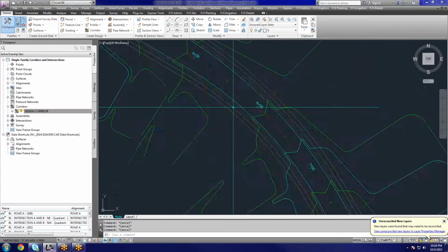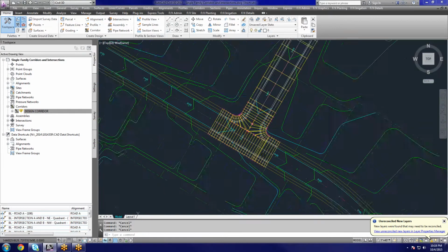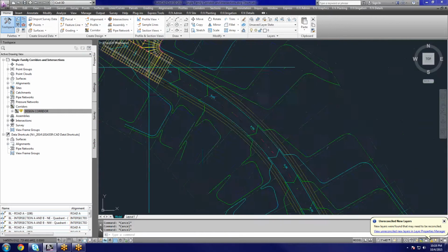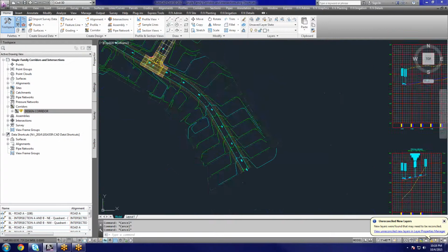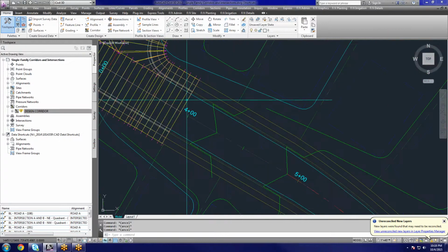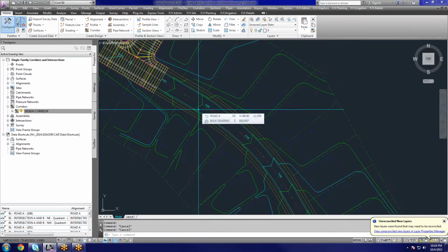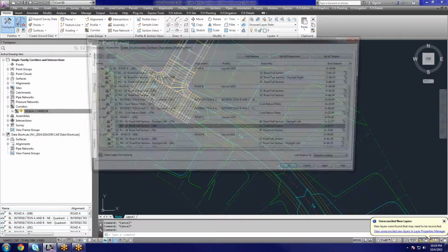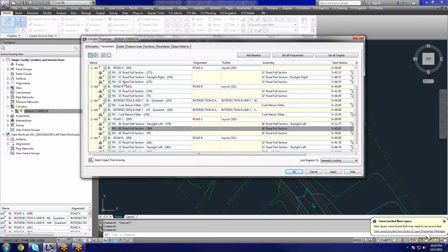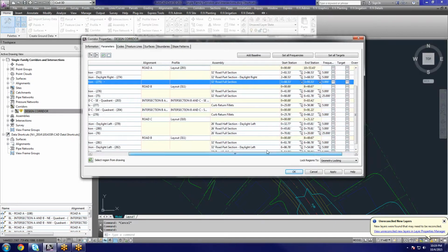However, I'm going to show you guys one more thing. I mentioned how this little segment of road is 32, and then it transitions from 32 to 26 right here. So I'm just going to insert a region after where this intersection left off to show you guys how you can have a segment of corridor transition from 32 to a different size road. It's a nice little thing to know. So we'll go to Properties, and we'll go to Road A full section, and I think this is where the intersection wizard left off.